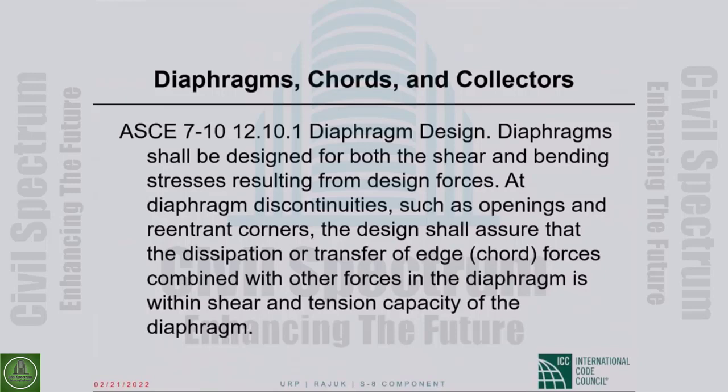I told you to start with that BNBC does not have these provisions. All it has is the two-slide text that I showed you, but diaphragms need to be designed, particularly for seismic design category D.